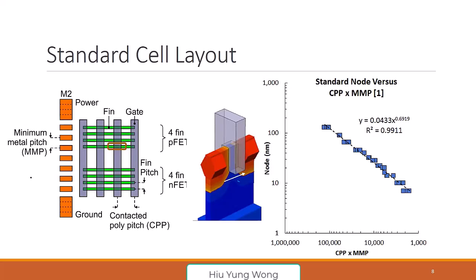So here I show you something called FinFET, a 3D transistor. You're not familiar with that? Yes, that is okay. Just treat this as a source. This is a drain. This is a gate. That's it. And it's just a so-called 3D because the gate wraps around the channel, turning it on and off. It is easier to understand than planar if you think of this as a water hose, right? Well, with a water hose, you just squeeze the middle part to turn it off and relax it to turn it on. It's exactly the same. But because now you have the gate, you use 2 fingers to squeeze the water hose. So you have very good control, making it on and off. And that is nowadays technology.